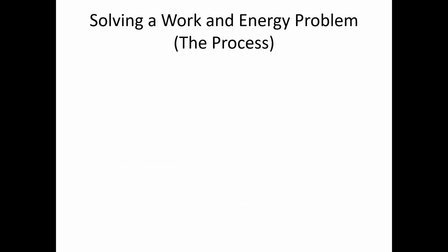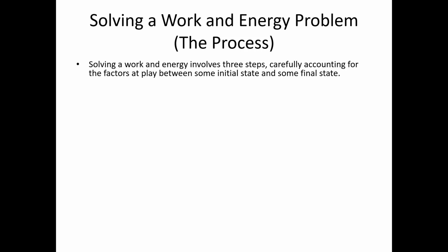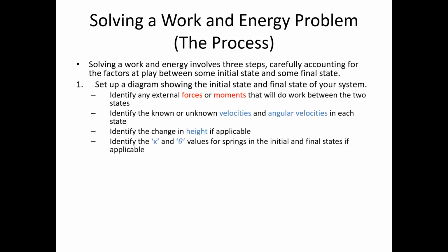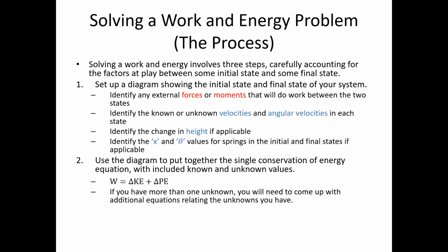As a review, the entire process with any of these work and energy problems: set up your diagram, show any forces or moments that are acting between the two states, show any known or unknown velocities and angular velocities, identify the change in height if that's applicable, and identify any x or theta values for springs, that is, the amount of stretch if applicable.